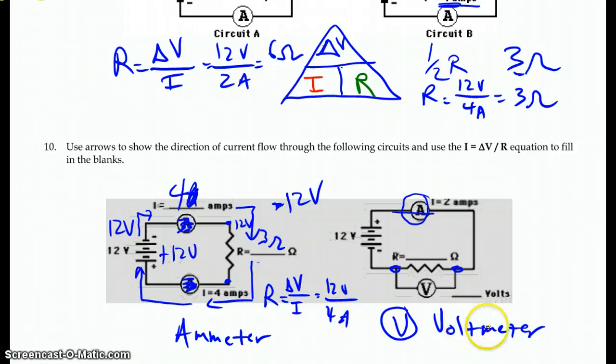To make it be correct, the voltmeter needs to have infinite resistance. And that way no charge will actually flow through it. So ammeters have 0 resistance in a perfect world, and voltmeters have infinite resistance. Voltmeters are always placed across 2 points, and they will measure the difference in potential between those 2 points. And then the ammeter will be in the circuit and will actually count the charge that's going through, and in a way count the electrons that are moving through that space.